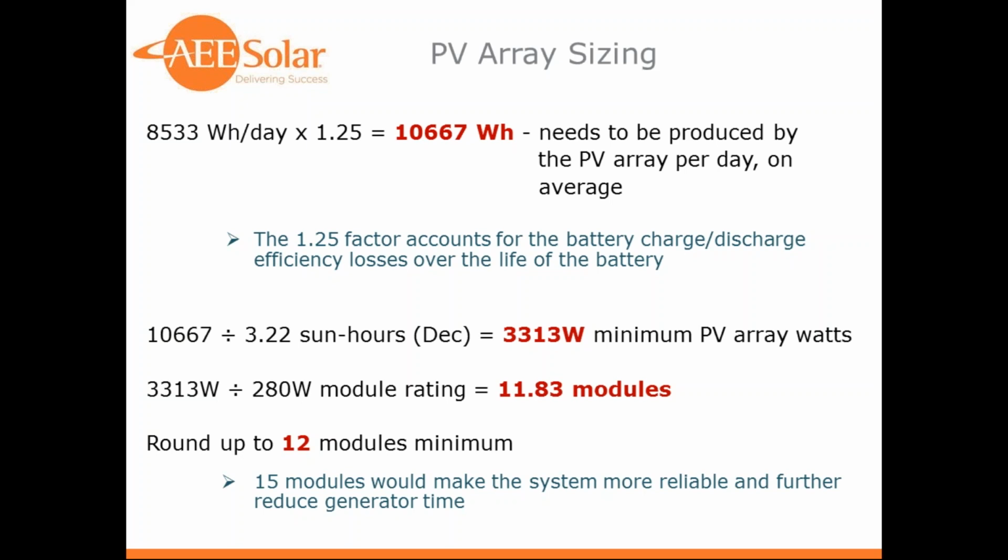So we generally use a figure of 1.25, which is fairly conservative, but we want to overestimate, if anything, rather than underestimate. So even though our consumption shows roughly 8.5 kilowatt-hours, we actually need to produce about 10.5 kilowatt-hours of energy in order to make that up and refill our battery and be ready for the next cycle. Pretty important number to do that, to make sure you calculate the losses in.